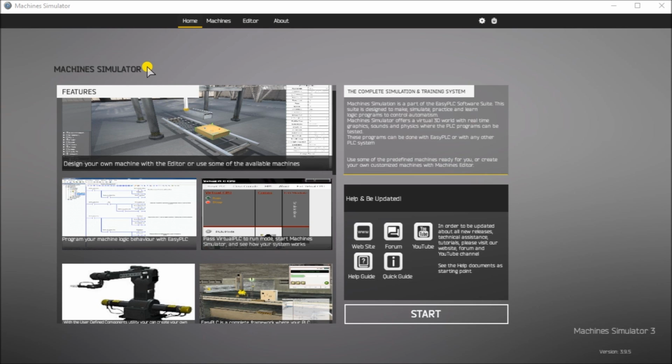Now, using the Click PLC, we will be connecting the simulator to the Gantry loader machine. This will be done using Modbus TCP Ethernet for communications. Using the 5 steps for program development, we will show how this is programmed. The logical sequence step will include a flowchart and sequence of operations. The sequence of operations will be done using indirect addressing in the Click PLC.